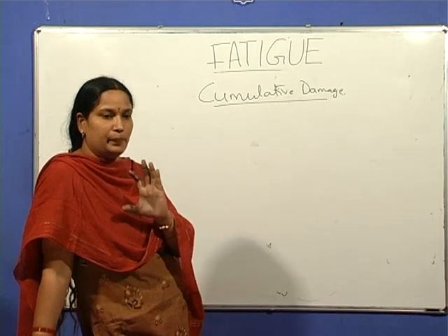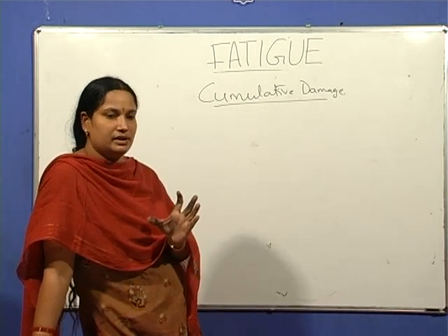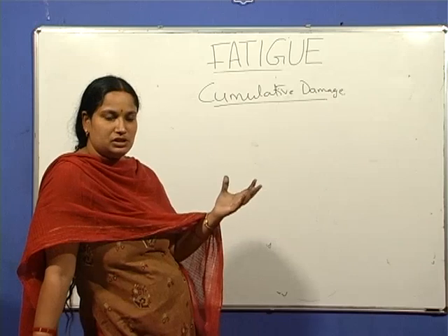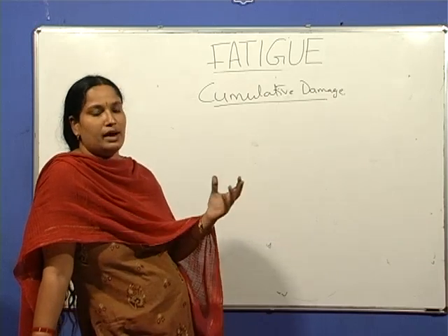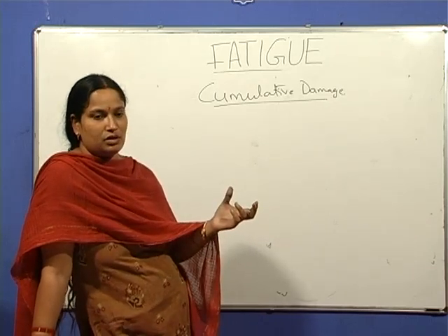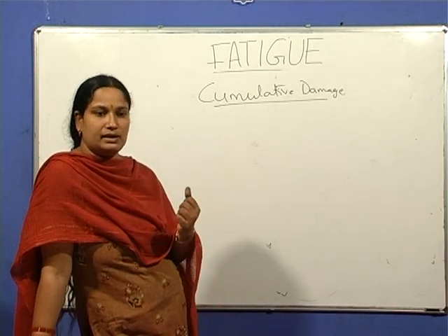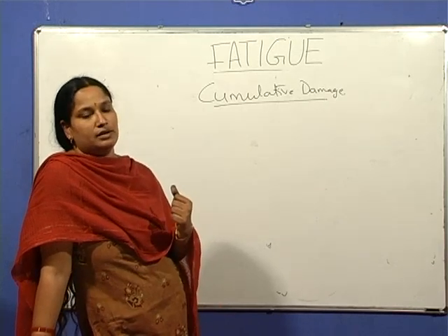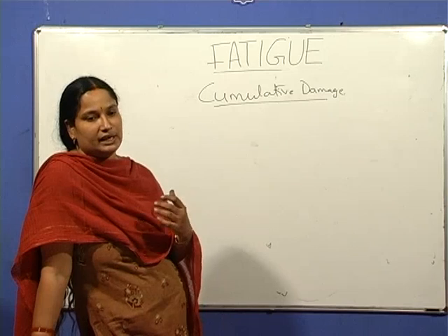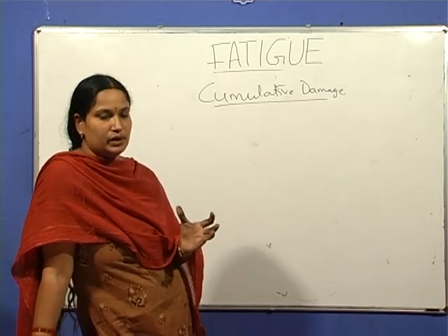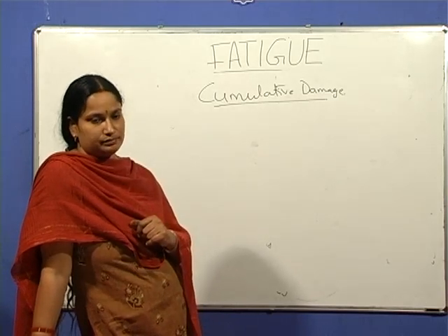That means one has to predict the life of the component which is subjected to variable amplitude and variable frequencies from the data obtained from the tests which are conducted at constant amplitude and constant frequency.